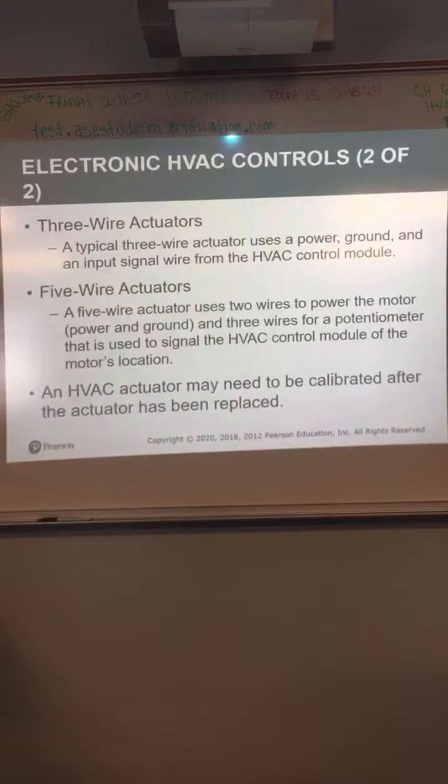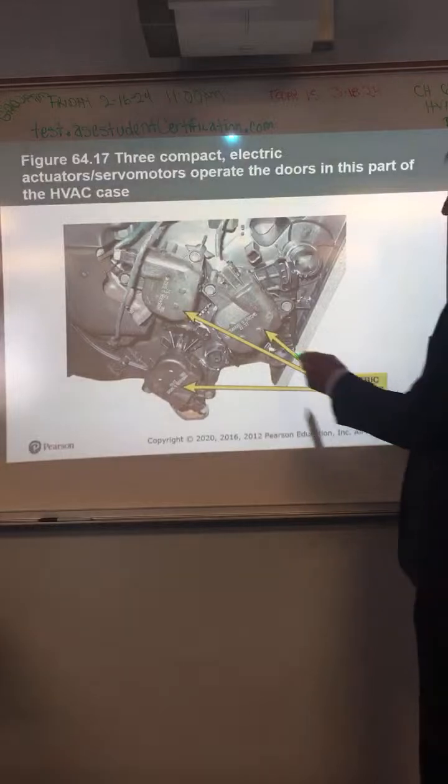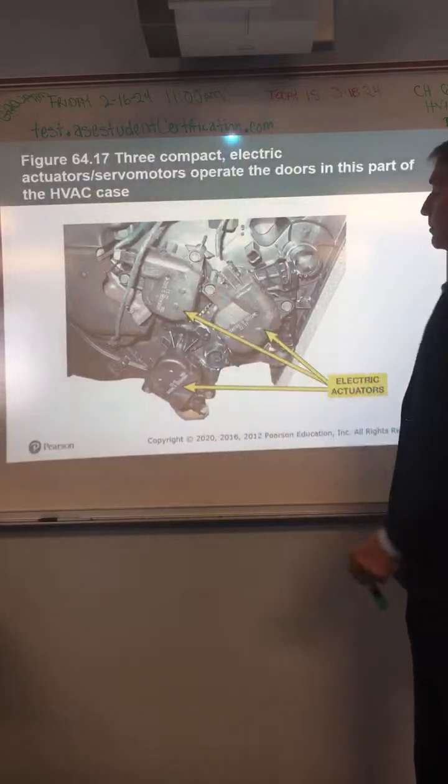The HVAC actuator may need to be calibrated after it's replaced. If it does, it's typically a simple procedure. Sometimes that can be done with a scan tool. Sometimes you can just turn the ignition on and off a couple times. It'll recalibrate itself. Okay. These are actually what some of those actuators look like.